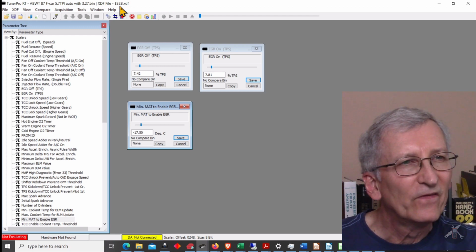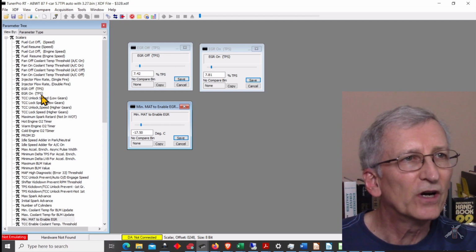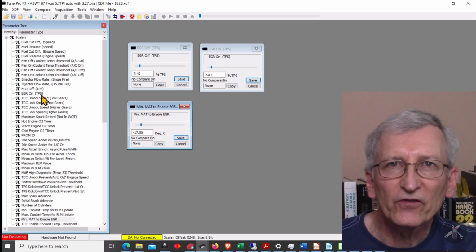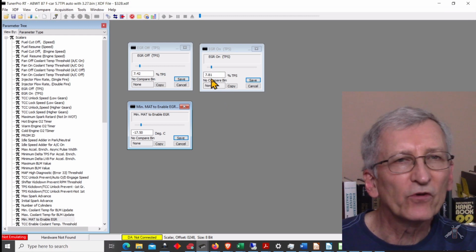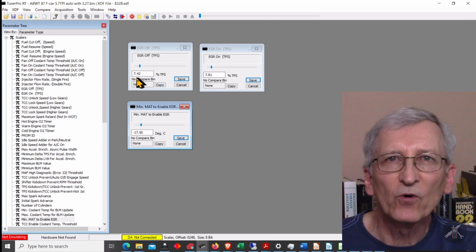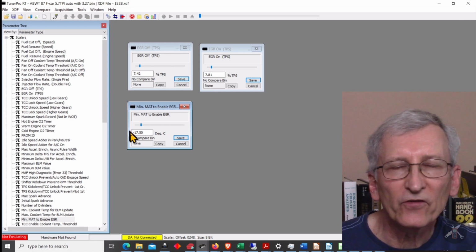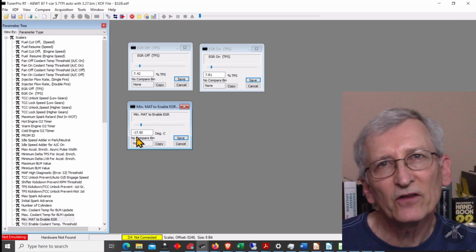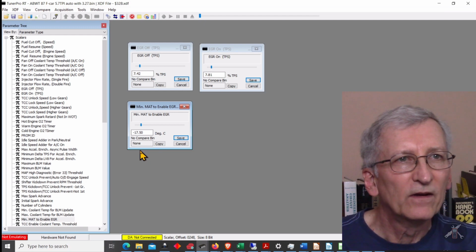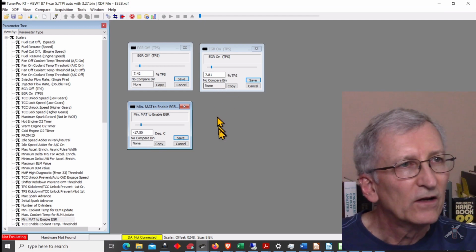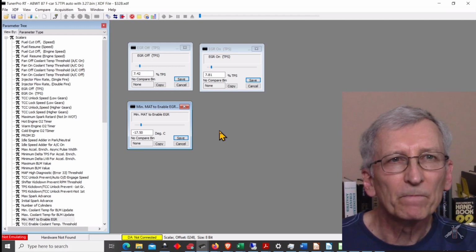And so then you go up to the scalars, up to the values on the top, and here's an EGR off and an EGR on. So it basically says turn on the EGR at 7.8% TPS, turn it off at 7.42. Enable EGR if you're above minus 17.5 degrees C. That's down around 0 Fahrenheit. So anytime you're above 0 Fahrenheit and above throttle, I think, I'm speculating, okay, and I know I'm speculating, but